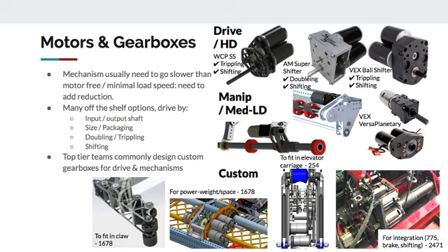So I highlighted a few down here. One of those might be, I just want a massive amount of power. There are actually a couple of elevators the last 2 years where you can see that there's 4 775s clustered around an input gear. I think this one also has shifting in the same gearbox. Yeah. It's super compact. It's a crazy amount of power that's sitting right there. But it's also quite a project to build something like that. So these are both elevator gearboxes down here. This picture doesn't come out that great, but I'll post some of mine.